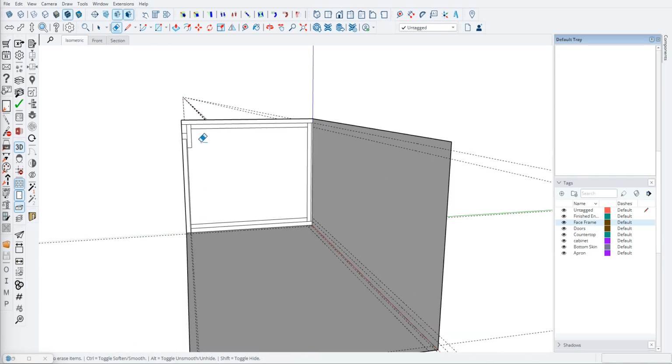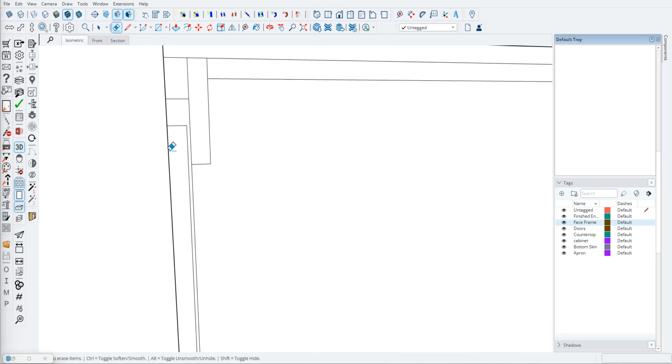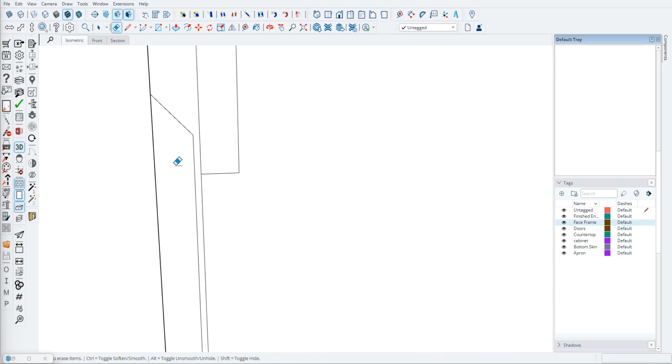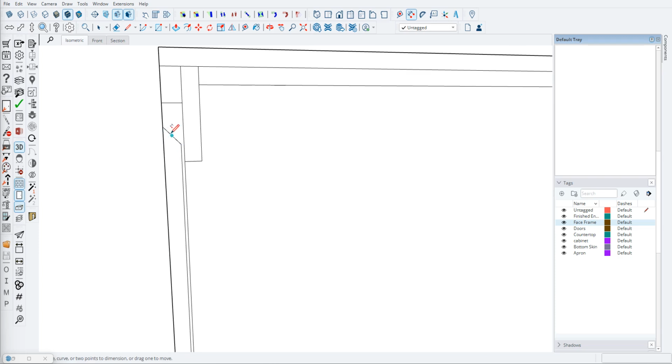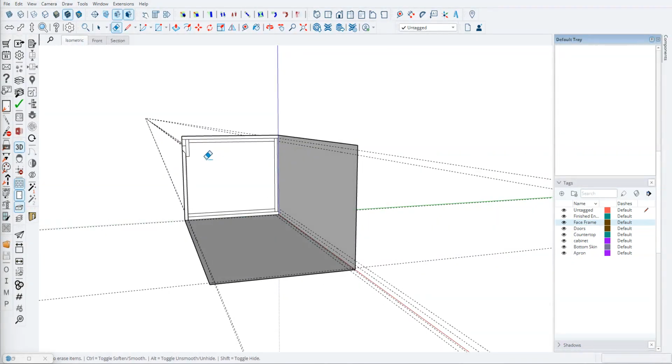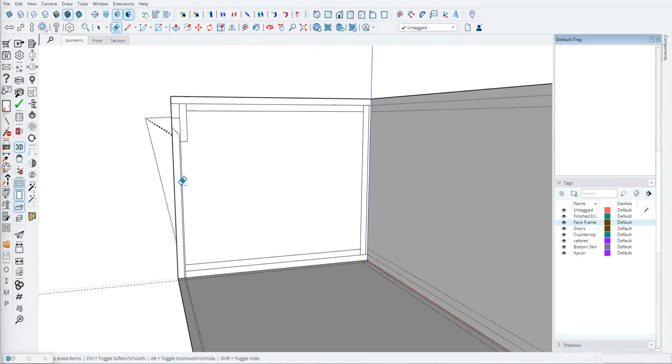All right. So this is kind of the section view. Now we know we're going to have a 45 chamfer here. So I know on a 3/4 door with the 45, it usually ends up being about 1 inch. Or actually, I'm sorry. We're just going to go ahead and draw down 0.75, and then create that 45 right there. What I meant to say is on a 45 on 3/4, this becomes pretty close to 1 inch. It's like 1 1/16. So there's the 45 chamfer. We can go ahead and erase that, and now you can start to see the section cut. I'm just going to leave that so it's all connected.